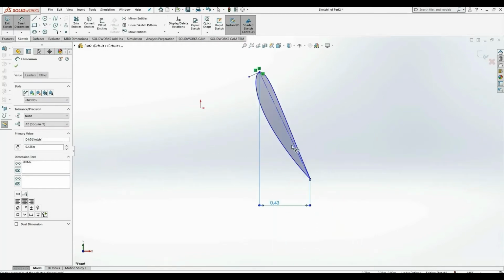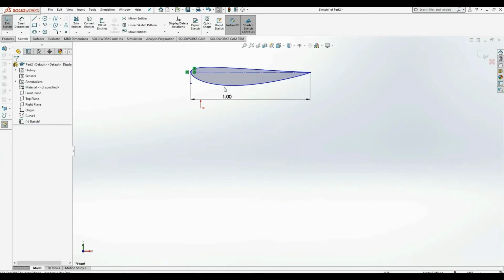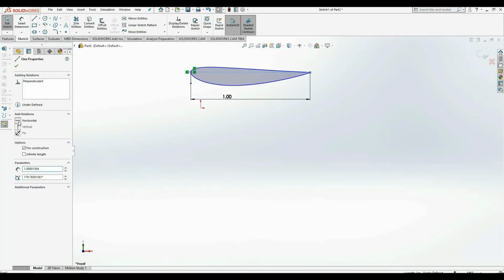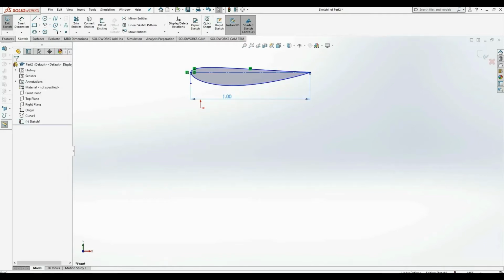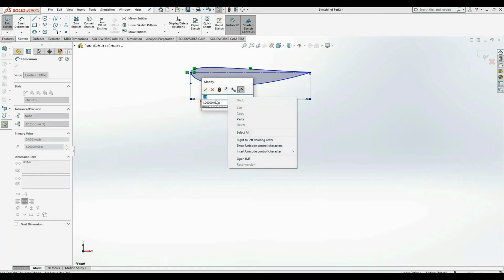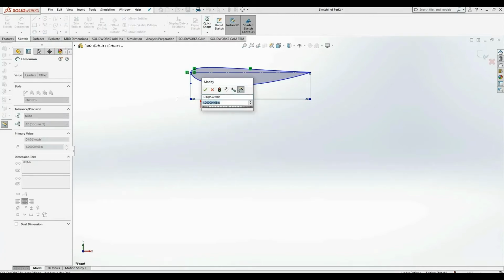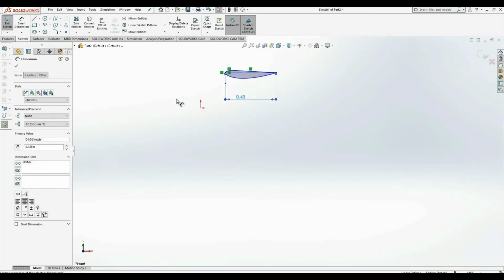Now what you can see here is one of the relationships was not kept, so the chord has to be inputted as a horizontal part, otherwise those dimensions will just change the angle to still meet the requirement. Again, I left that there to highlight a potential common mistake. So now let's try again with that relationship back in.